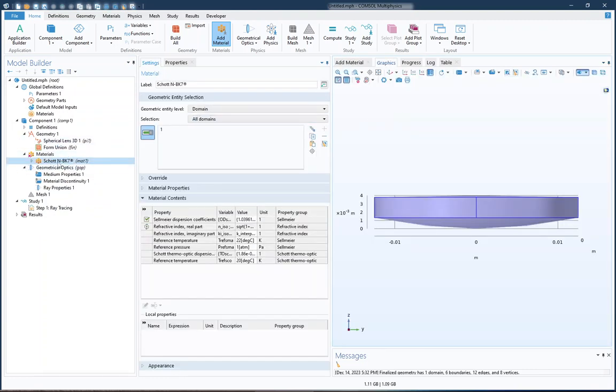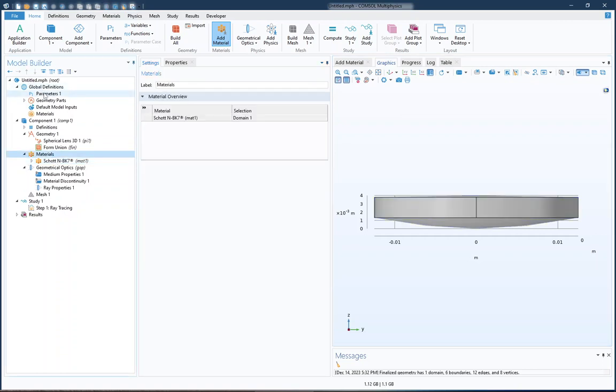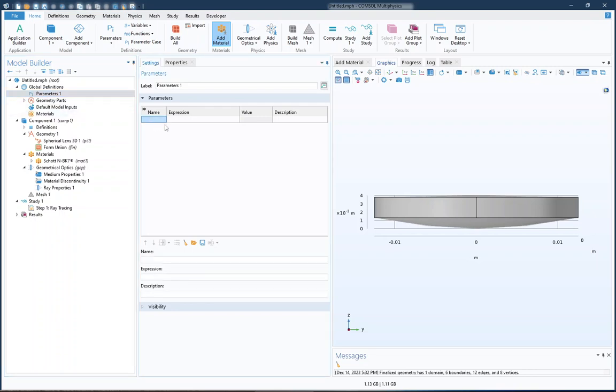A weird kind of thing that we need to do when we're using this material in specific, and some other materials as well. We actually need to define the wavelength, which is the frequency, and we will define it to be 588 nanometers. And basically this will tell this material what wavelength it is, so then this knows what index of refraction value that it'll use. So that is basically how it'll work.